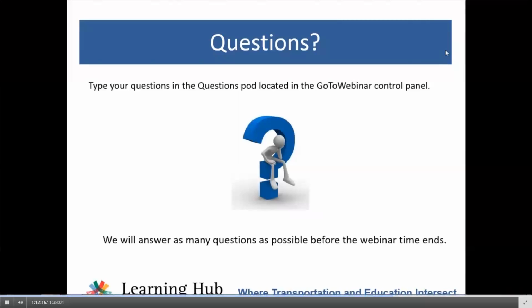The thing I would really like to emphasize is to bring it back to the broader ICE framework, where even if the roundabout level of service in the peak 15 minutes may be a little bit worse than that of a traffic signal, the ICE framework really allows the roundabout and some of these other intersections to shine, because they will end up performing so much better on the safety perspective, so much better on the life cycle cost perspective, that hopefully some of these slight differences in the level of service thresholds are going to be well made up by the fact that some of these intersections have such tremendous safety performance.